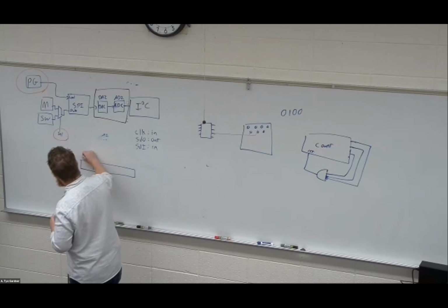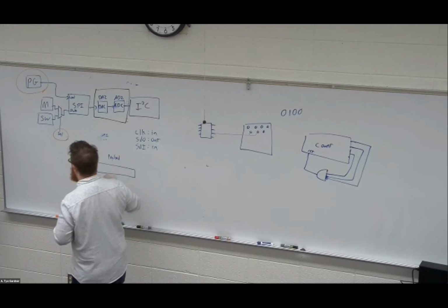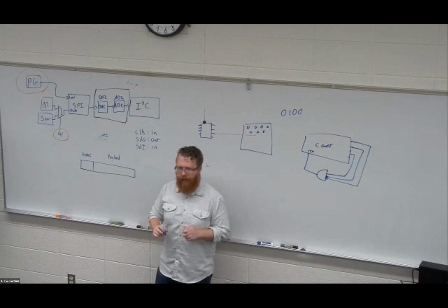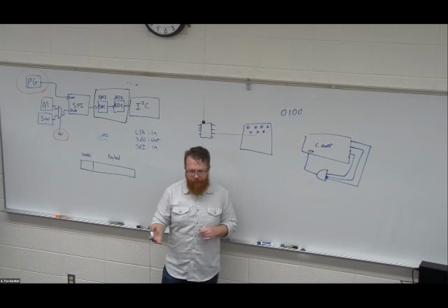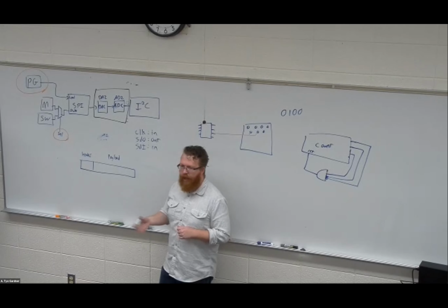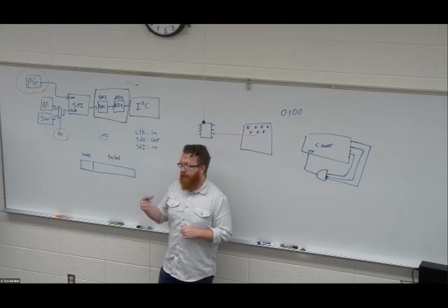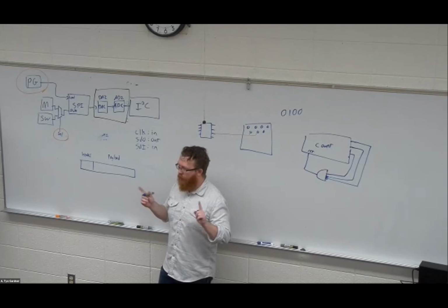So we're going to have that same kind of concept as the SPI, right? where we're going to have some header and payload, right? In the case of the SPI, what that header contained was configuration data, meaning how do I want the device to behave? Because in the case of your DAC, you may be using a battery powered device and you don't always want it on.